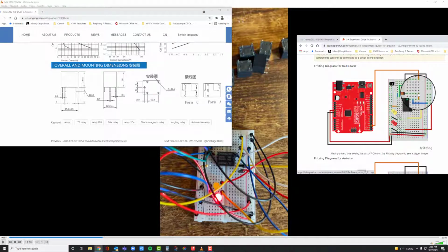Oh, the white wire is this one here, and then there's a blue wire that goes here. So these 2 wires right here on this diagram would need to go lined up on this pin over here. So they would be lined up over here on the top with this pin, and then these 2 wires, this one here that goes over to the transistor and this one here that goes to the diode, those 2 would need to be lined up on the bottom over here, and then the resistor here should plug in to this line here. So it would be kind of dead center wherever that pin is connected here.